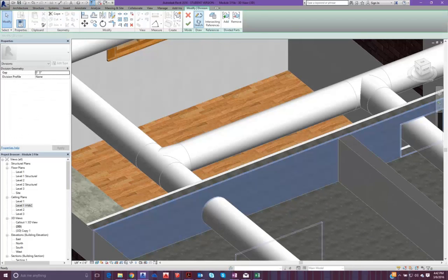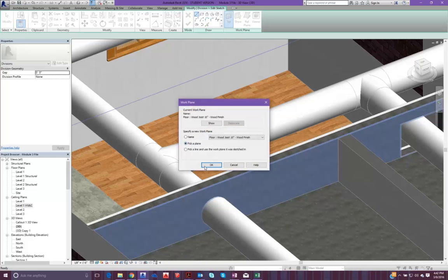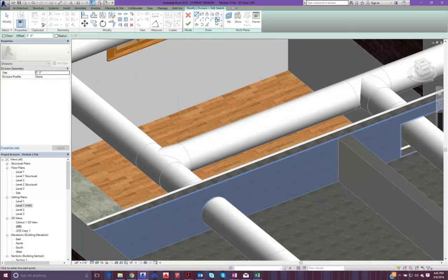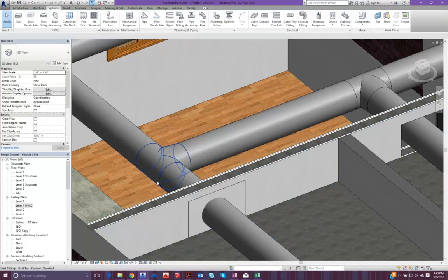and let's go ahead and edit our sketch. Set the reference plane to pick a plane, and we'll pick this front plane, and we'll hit this little rectangle. We'll go from right here to right here, and we'll hit the check mark, and we'll hit the check mark again.